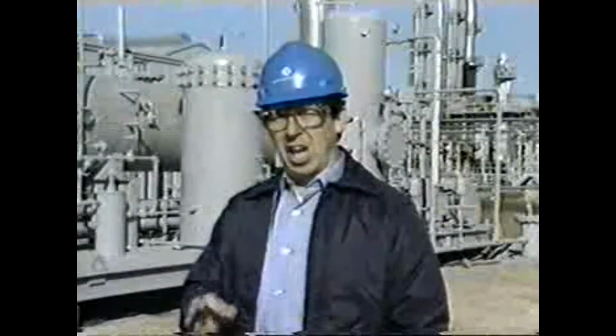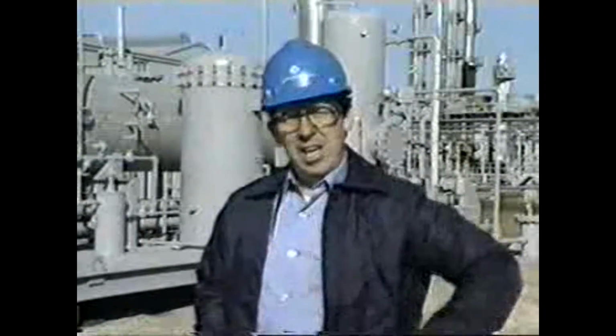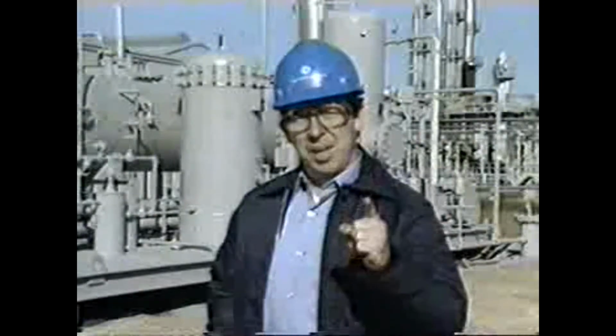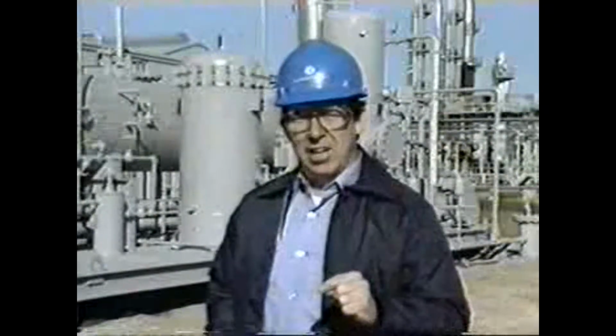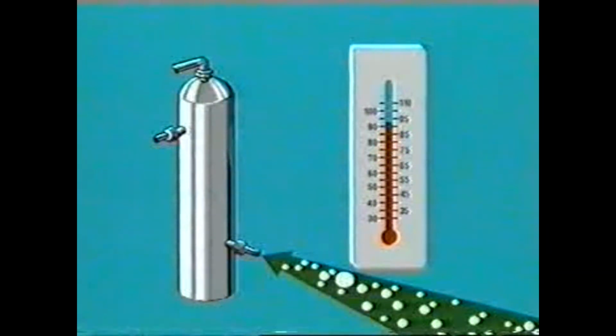Various temperature and pressure conditions affect how efficiently the glycol dehydration unit can operate. First, let's look at operating temperatures in the contactor, reboiler, and still overhead. Then we'll look at operating pressures. In the contactor, the temperatures of the inlet gas and the glycol affect the amount of water removal from the saturated gas. Now, if you recall, at constant pressure, natural gas can hold more water as the temperature of the gas increases. And what does that mean?